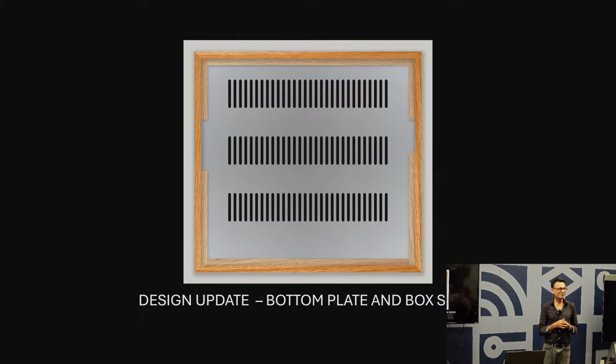And I thought, that's pretty thick. So I said, well, what if it's 2 millimeter? And by the way, it said with 3 millimeter, the center of it will sag like 0.05 inches or so. It gave a very specific answer to my question, right? So I said, well, what if it's just 2 millimeters? And it said, well, based on 2 millimeters, it'll sag like 0.1 inches. And I thought, well, that's good enough because it's going to be screwed around the edges. So anyway, I find so many uses for ChatGPT, and I'm sure like all of you have. And assisting with design is one of them. Okay.